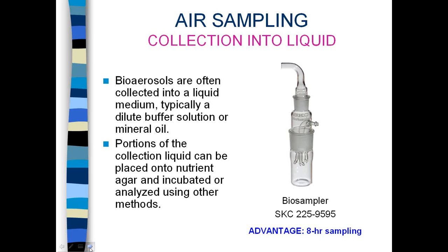Bioaerosols are often collected into a liquid medium using an impinger-type device. Liquid collection allows for a number of different analysis techniques. Shown here is the SKC biosampler that is normally used with a microbiology-grade mineral oil called SKC Biotrap. The advantage of the SKC biosampler with Biotrap is that sample times up to 8 hours can be used. The other methods we discussed so far in this presentation had much more limited sample times.